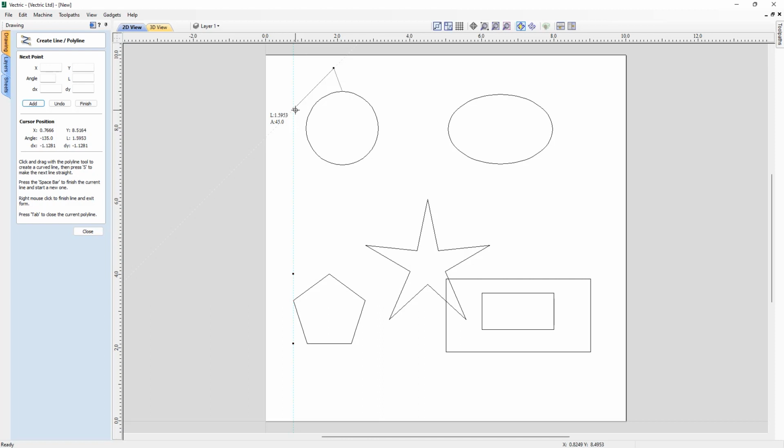Right then, we're going to look at snapping to tangents here. If I bring my cursor down and press T on the keyboard, it snaps to the actual tangent that we've got there. Then if we pull out, you can see we've got a line here that's perpendicular to that tangent, and we can see that right angle there, and we can click like so. So there's lots of different ways for us to draw up.